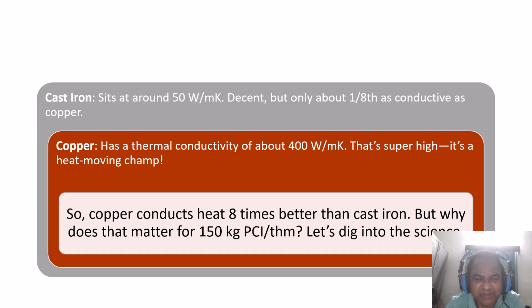As this slide shows, copper conducts heat 8 times better than cast iron, and as heat load increases, our property requirement demands improvement. At this level we need to absorb heat from the combustion area and dissipate it to the system quickly, and for this, as we have already shown, cast iron stave will not be very suitable.